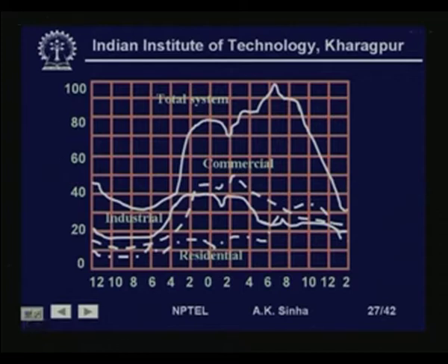Well, in a power system, you have the turbine and the generator set. These are rotating at high speed. So, the inertia of this rotating mass stores a large amount of kinetic energy. When you switch on a supply, immediately this power comes by getting extracted from this kinetic energy of the rotating mass, and because of this extraction the speed of rotation will slow down, that is, the rotating mass will experience some retardation. So, this is what we see in terms of change in frequency, or reduction in frequency.